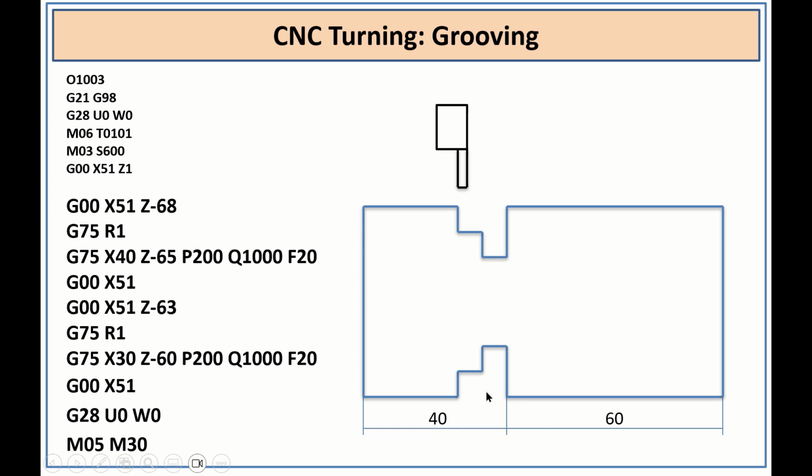Generally this is 60, and here it is 70. If I mention 70, what will happen? So now I have taken this right grooving tool, and I am taking this right groove or right edge as a reference. If you take this as a reference, the advantage is it can perform accurately at the end of the cycle to 60. So that is why I have taken this edge as a reference.